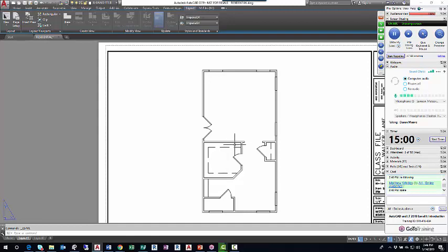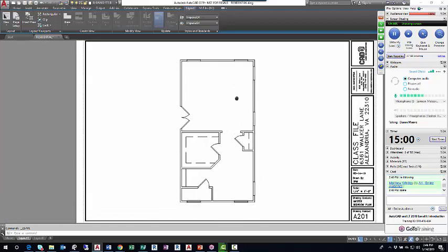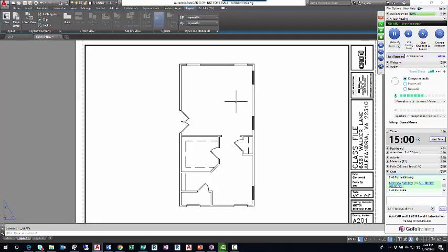If I've got text that says shelf and pole in one part of my drawing that's 3/32 of an inch high when I plot it, then everywhere I use that text, it should be 3/32 of an inch high. Otherwise, anyone reading my drawing can say, hey, what are you trying to say? Why is this a different height? So it kind of allows you to create a uniformity in your drawing. So we'll create 3 text styles in this drawing, one for the dimension, one for notes, and one for the room name.